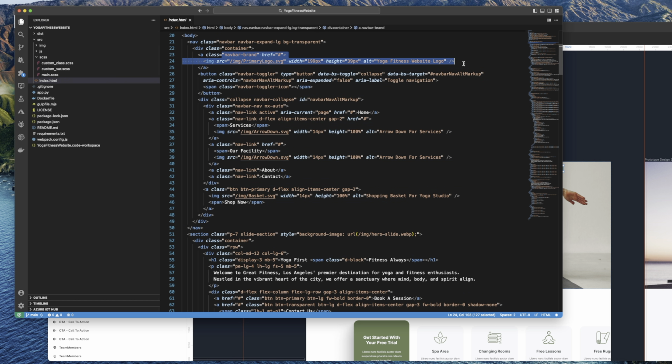All right, so number 7 is nested auto layouts for complex structures. The nice thing about auto layout is you can follow a specific front end framework, something like Bootstrap. And the great thing is you can use its nested layers and groups and frames to be able to follow, let's say, the grid structure or the column structure of Bootstrap itself. Now, what I normally do is I like to rename my groups and I like to rename my layers to follow closely to that of Bootstrap. Again, this comes back to point number 6, where the entire design to development process is much, much easier if you follow auto layout.